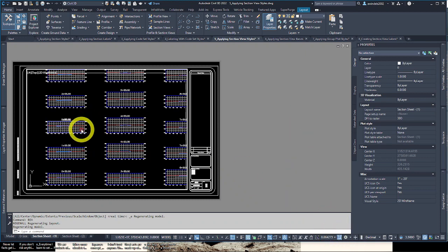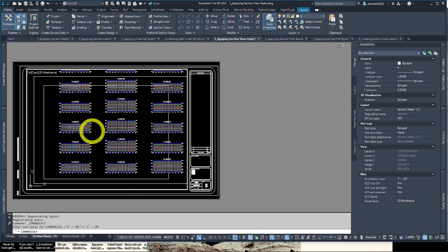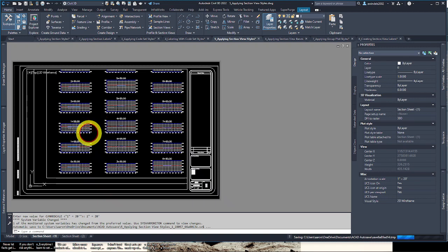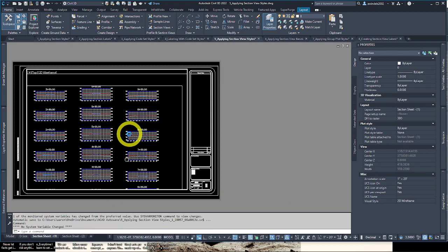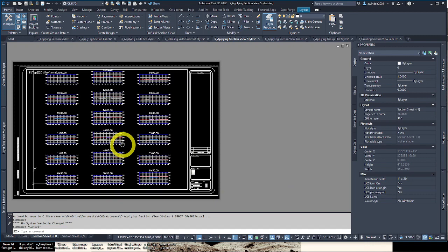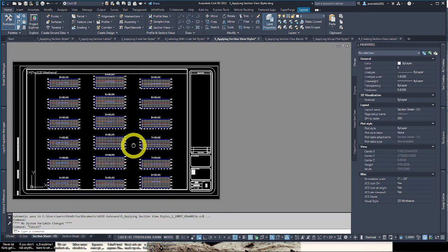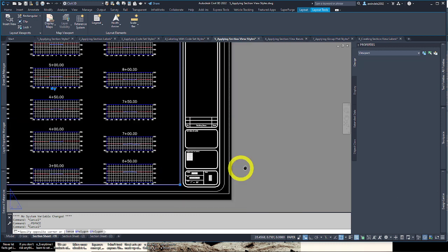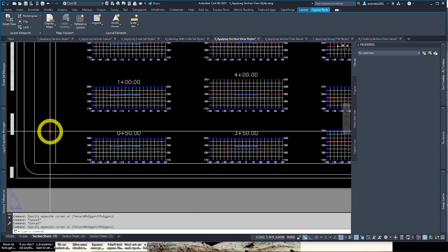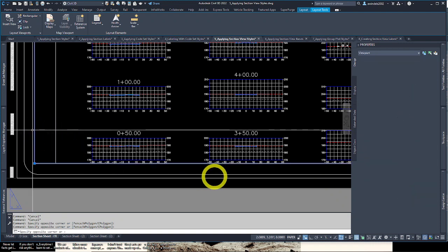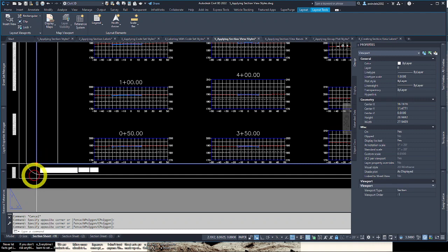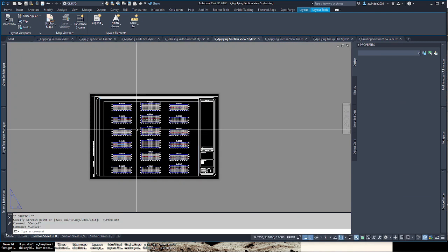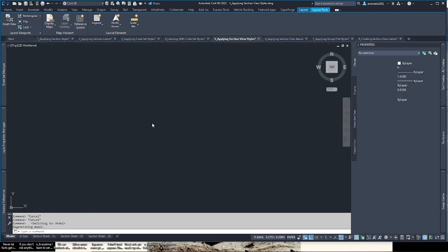Let's say they're 1 inch equals 20 feet would be a pretty standard section view scale for a sheet. And we're starting to set up our final sheet here, which this class could use maybe a little more emphasis on drafting and setting up sheets, but we get it ready here. Let's just say it's looking pretty close, and I lock the viewport again. And you can further edit your viewport. And this one isn't ideal. I would have made it a polygon, but it is good enough for display purposes. And there we go. So that's just showing you the power of that.